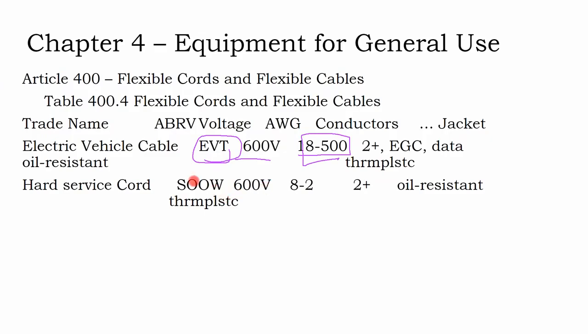I'm used to using welder's cable inside of large battery banks for ease of wiring. Might have to look at the EV cable instead. There's a solar cable too. It's called PV cable. It's high voltage, with a super thick jacket, for exposure to sunlight, high temperature, and wet environments.